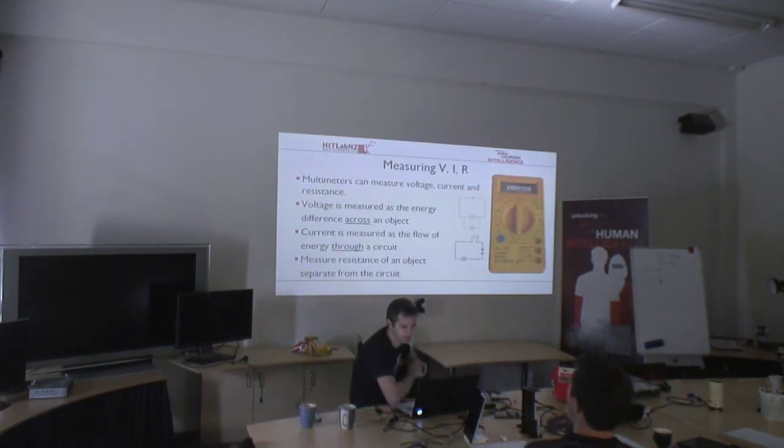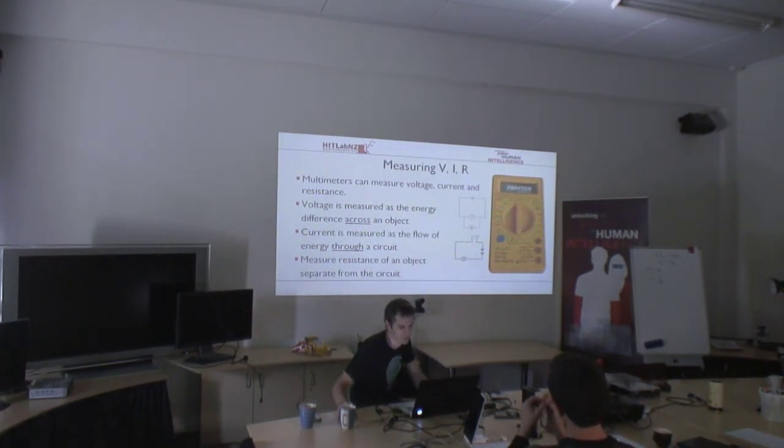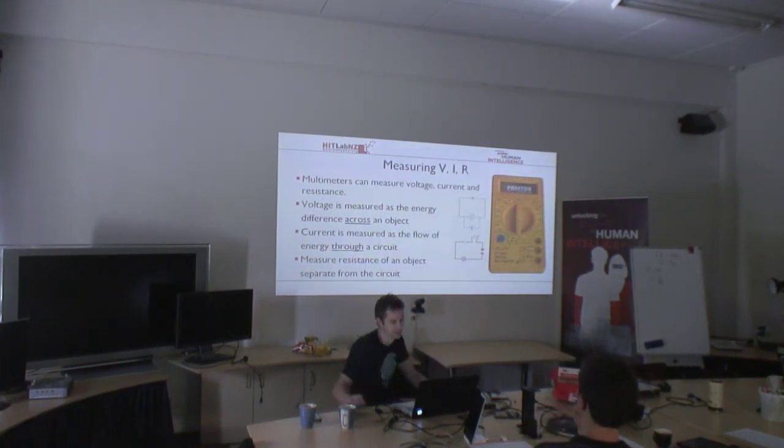So, measuring voltage, current, and resistance. Here is another digital multimeter like the one we saw before. This one's a little bit different from the one we have because here you actually have to specify, when you're measuring voltage or amperage, the maximum cutoff. DCV is DC volts. If we're using a 9-volt battery, we'll say it's never going to go above 20 volts, so we're fairly safe here. Even a car battery is only 12 volts.